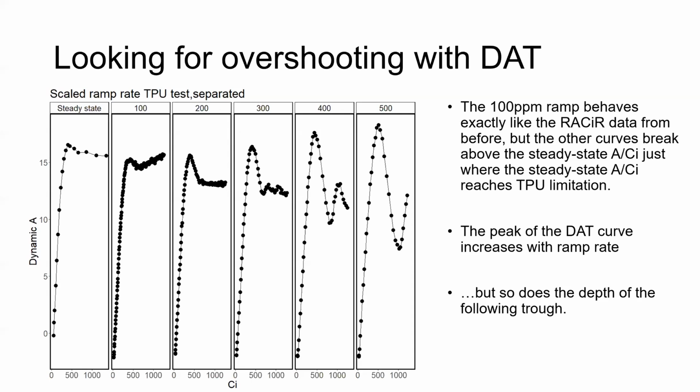How does DAT do with water and Ci estimates? So this is actually a pretty interesting question. Generally speaking, if you're doing a DAT curve, the water isn't changing fast enough for it to be a problem. Now, the dynamic equations are prepared to handle dynamic changes in water. It's just a question of whether you should be using the dynamic measurement of water or not. I would probably just use the steady state measurement of water. It's certainly fast enough. And then if your dynamic calibration isn't perfect, it doesn't make a difference. But if you use the dynamic measurement of water, no problem as well. Just make sure that the calibration works out.